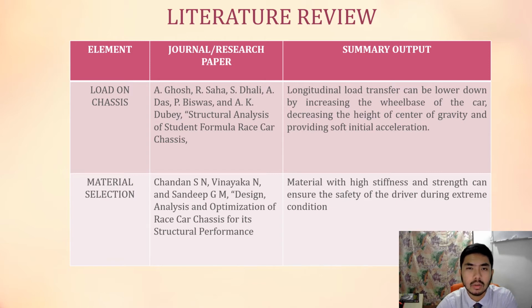As we know, there are many loads that occur on the chassis. There are lateral load, longitudinal load, and asymmetrical load. We also need to find the torsional stiffness and also the bending stiffness. And second is about the material selection.